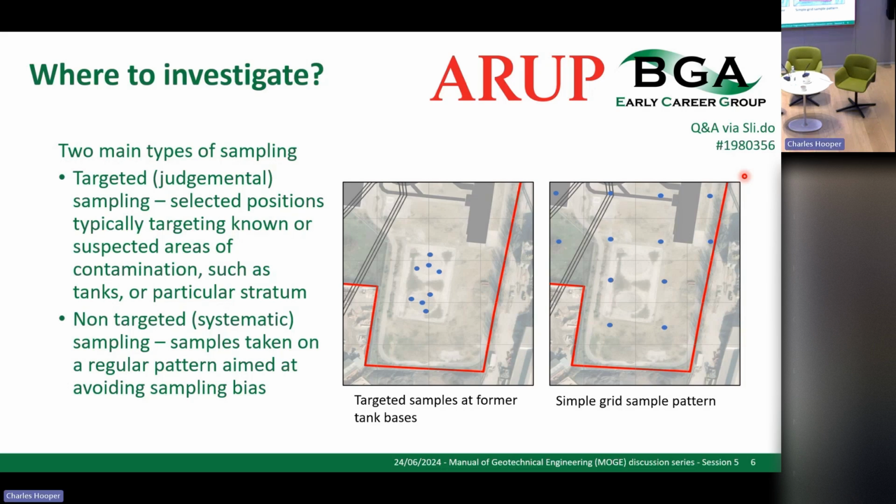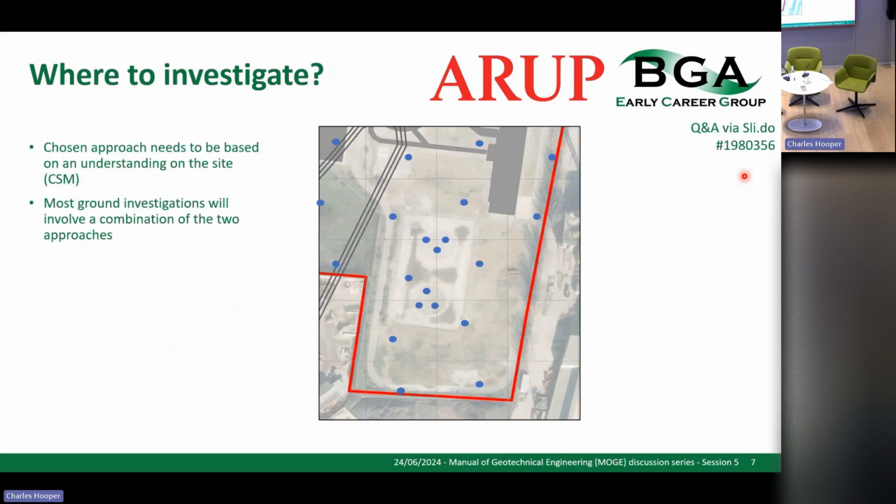The other thing to note in this particular instance, in the top left corner, the second one in, where the 3 lines are, that's HV cable in this instance. So we can't actually put that borehole where it's shown on this plan. We would have to move it. So we've naturally just instantly lost our unbiased nature that was derived from the scheme. At the end of the day, most sites are going to be a combination of the 2.